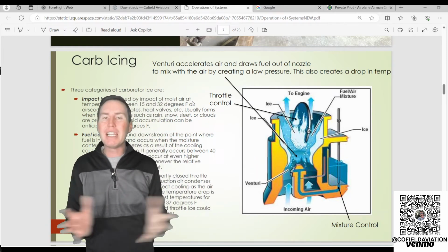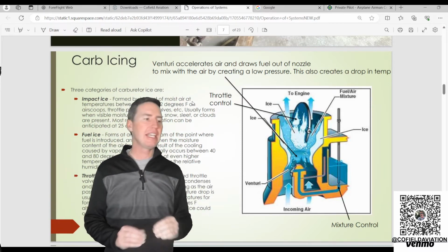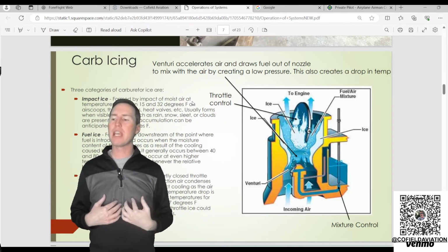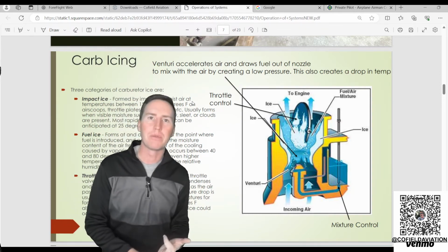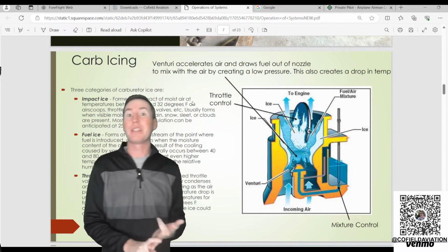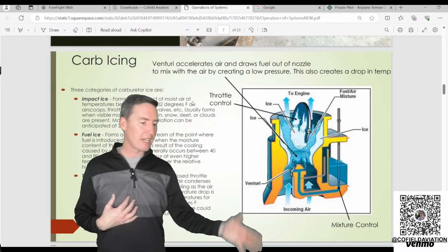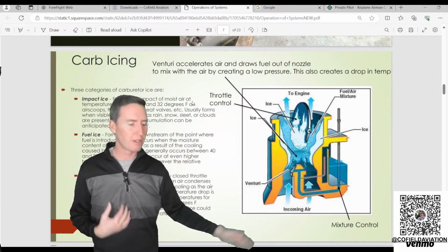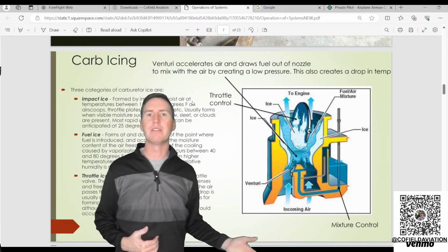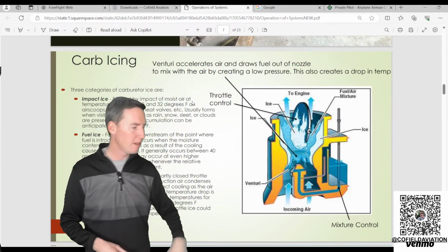But again, we may not know that's the issue, right? Anything with that engine, the only thing we have control of is fuel, fire, and air, right? So it's got to be one of those three things. So what do I have access to for fuel? Well, I have a fuel selector, I have a mixture, and I have a primer. Okay, so I'm going to check. I'm making sure I'm getting fuel, enriching the mixture if it's maybe too lean or something like that.